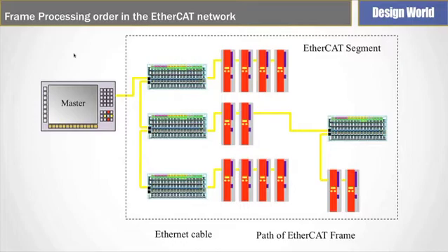This allows us to do efficient slave-to-slave communication for things like our safety protocol, and also allows us to have asynchronous communication if a slave wishes to request a firmware update or has something to put onto the frame. It can request asynchronously, and therefore allows us more efficiency with the bandwidth.